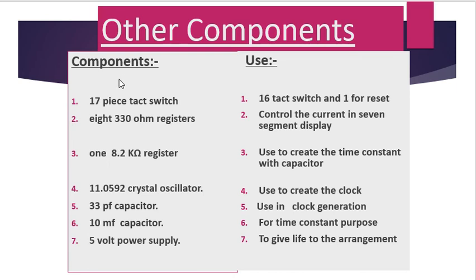Other components we use are 17 tact switches, 8 330 ohm resistors, 1 8.2 kilo ohm resistor, 11.0592 MHz crystal oscillator, 33 picofarad capacitors, a 10 microfarad capacitor, and a 5 volt power supply.